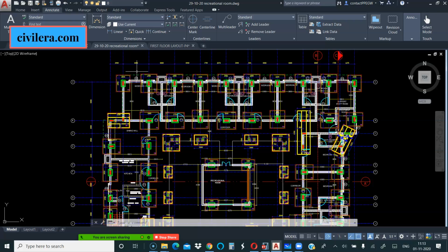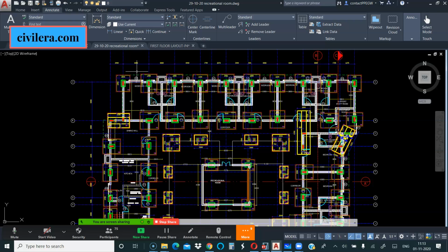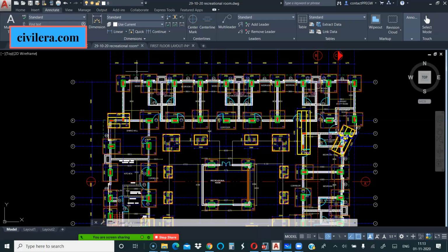If it's these kinds of buildings in zone 2, you can go with maybe 230 by 500 or 600 size for the column. 450 you can try, and then after your first analysis you can keep on making changes. You can increase and find out the optimum size. It's easy to do that. There are many other rules, we will discuss that some other time, but this is an easy rule.